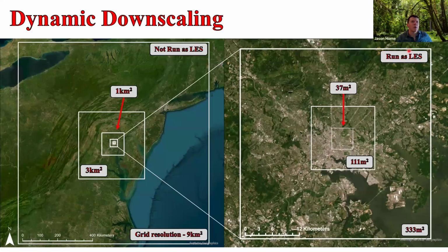And you're going into LES mode here, where you're switching from a PBL scheme to an actual LES representation of the flow patterns, doing 3D diffusion of the turbulent motions. And we're beginning to resolve these large eddies. So again, we're tunneling down specifically over this neighborhood in downtown Baltimore that has a lot of cultural significance and has really been a focal point of the BSEC project at large.